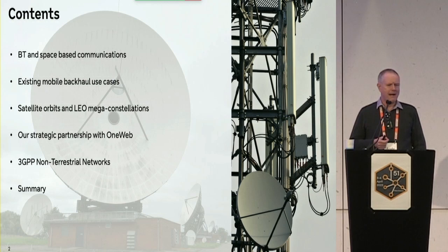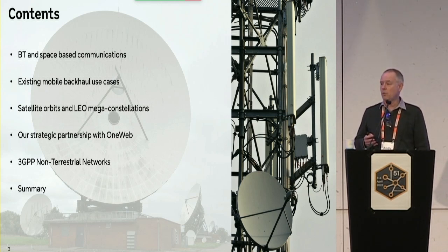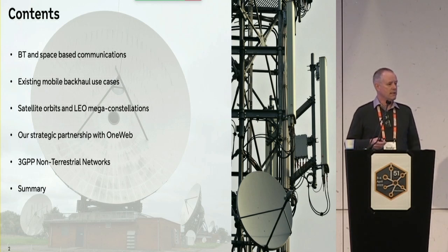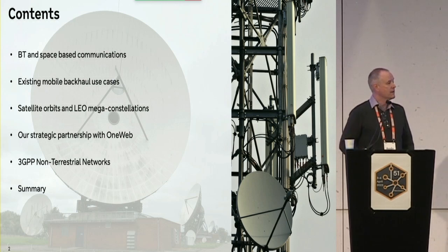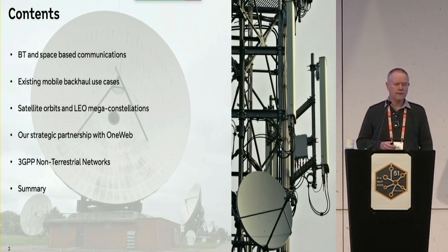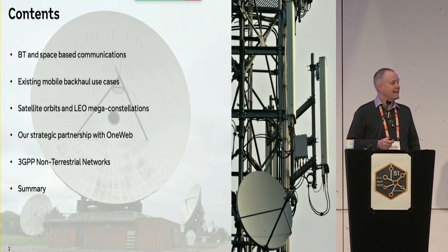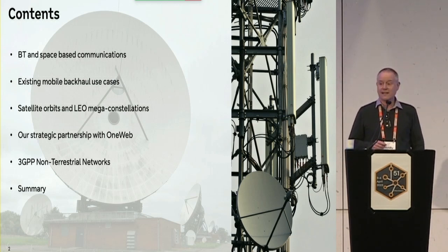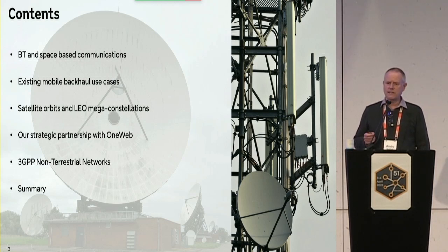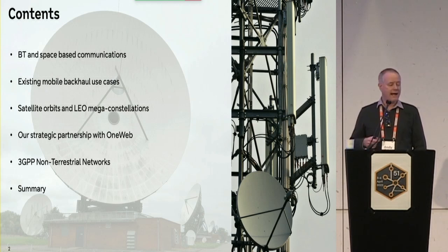But I'll start with a little bit of background about BT and space-based communications, look at some existing use cases for satellite and mobile backhaul. When we talk about mobile backhaul, we refer to the connectivity between a cellular radio base station, so the tower or column or rooftop radio site you see, and the core network. So traditionally, we deliver that connectivity with fiber optic cable or microwave radio, but in some cases we use satellite, and in other cases we deliver it with terrestrial, but use satellite to provide resilience, so a higher level of